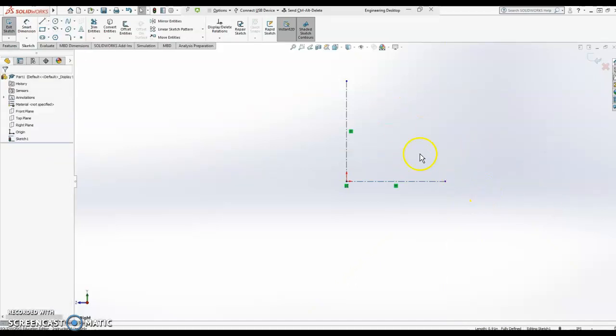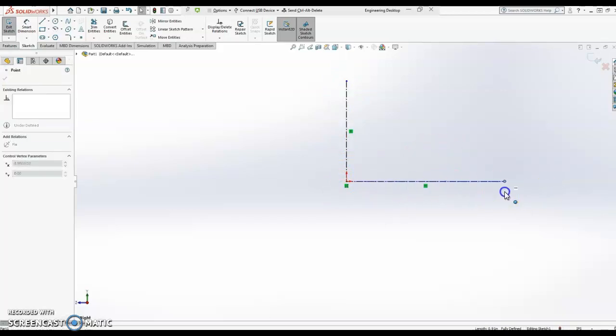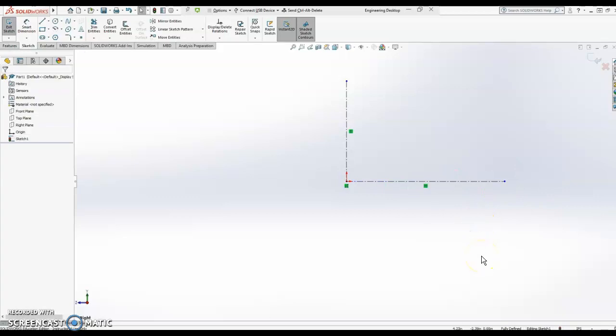Now notice that these lines of symmetry are black. They come in black because I've got a horizontal and a vertical ground, which is exactly what I wanted. The blue one I can grab that point and move back and forth because it is unconstrained. I'm not so much concerned with where the center lines end, because they are just there for construction. So size is not important. I'm just going to leave them there.